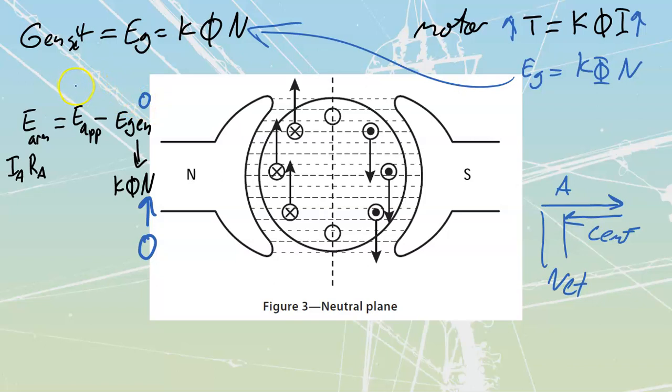voltage, let's say that this is, I don't know, 120 volts DC. I would have 120 minus 0, which would tell me that I would be dropping all 120 volts over top of my armature. And if my armature has only a small value of resistance, let's say that the resistance is 2 ohms, that would mean I'd be dropping 120 volts over top of 2 ohms, which would mean that I would have 60 amps of current initially flowing through here.